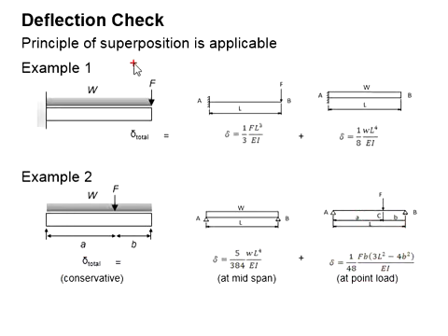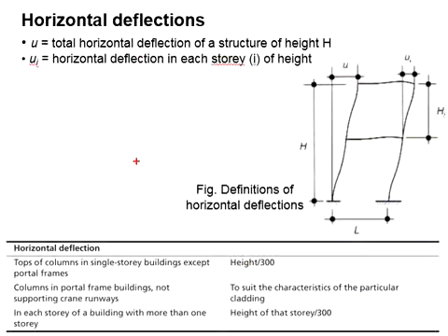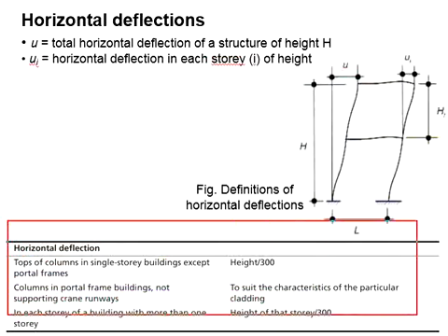If you wish to go for a more precise manner, you may determine the total displacement at the midspan and compare it with the total displacement under the point load, and the larger value is obtained. Both will have the total displacement less than indicated here. The limit for the horizontal displacement is given here, also in the National Annex.